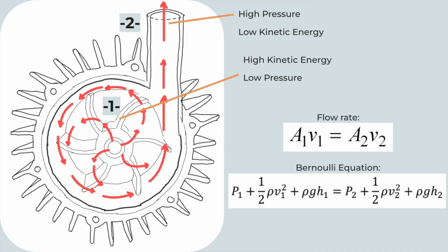The rotating impeller accelerates the fluid centrifugally, and an increase in the cross-sectional area causes the fluid to decelerate since the flow rate must remain constant, giving us a region of high pressure and low kinetic energy at the outlet and high kinetic energy and low pressure at the inlet. A limitation in our machine is that there is a uniform cross-sectional area in our volute casing, whereas most centrifugal pump volute casings are uniformly increasing in cross-sectional area, which minimizes the head of our homemade pump.